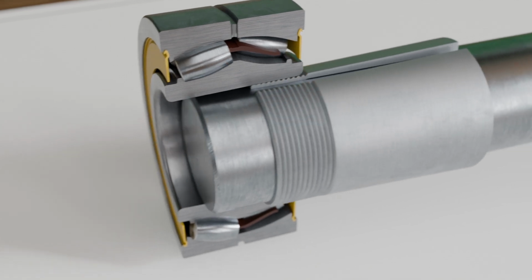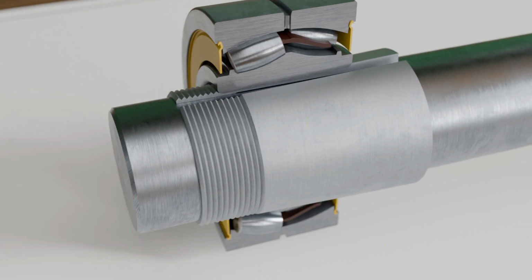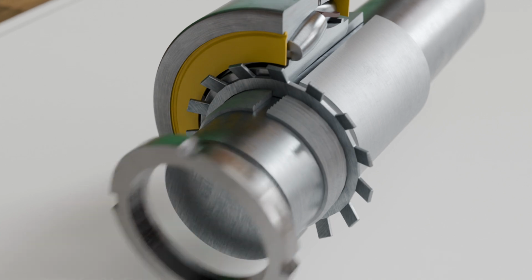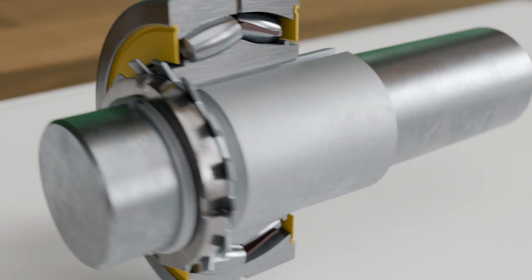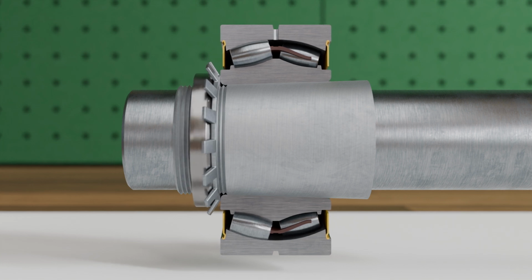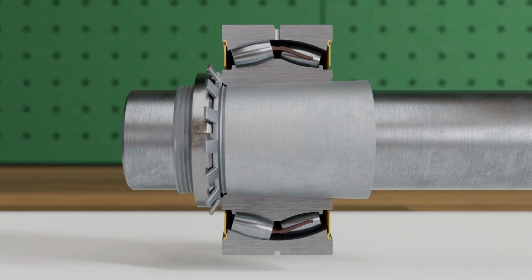First, the slotted adapter sleeve with a mounted bearing is pushed onto the shaft. Then a tab washer is fitted and a slotted lock nut is screwed onto the thread of the adapter sleeve. The adapter sleeve acts like a tapered mandrel that pulls the bearing onto the shaft. By pushing the sleeve forward, the inner ring expands slightly, allowing the bearing clearance, which means the gap between rolling elements and the outer ring raceway, to be precisely adjusted.